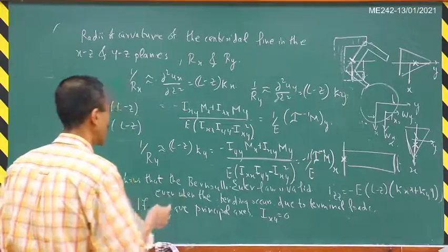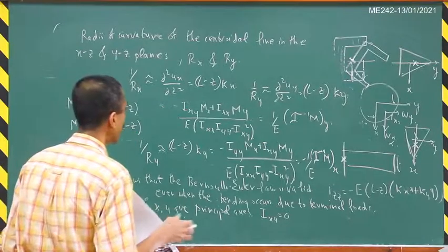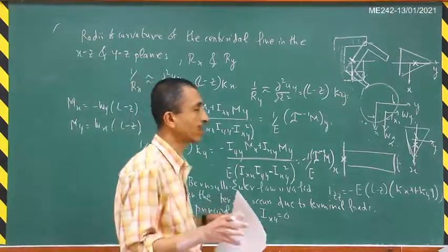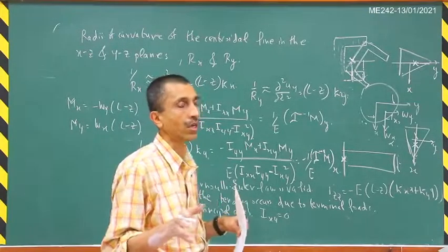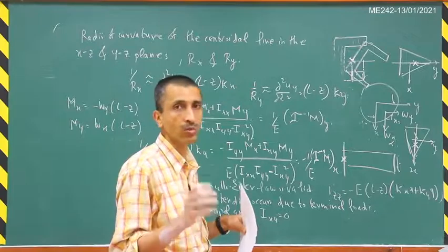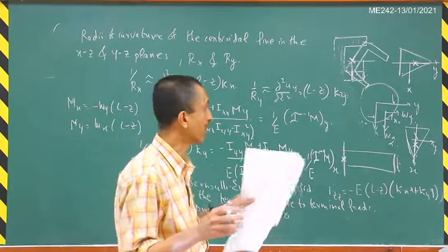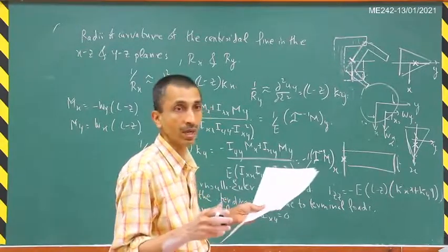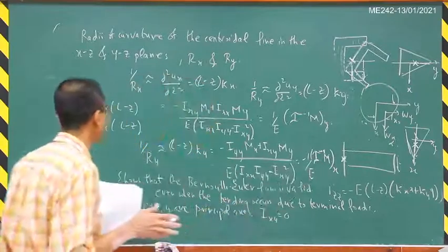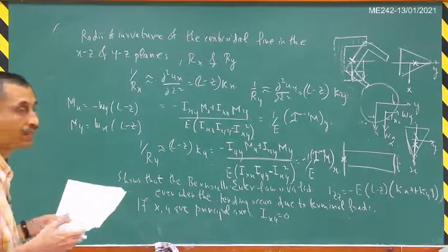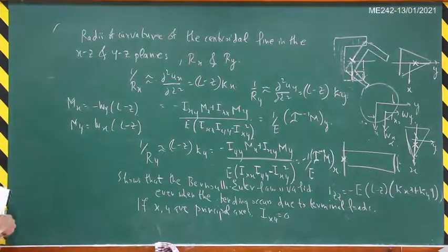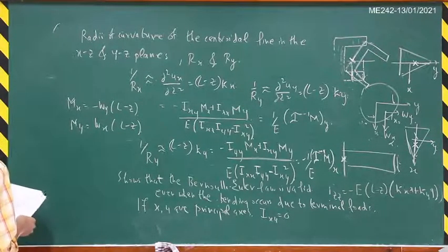So basically the same principle that guided us for pure bending can also be used in this particular case when there is bending by terminal loads, because even in this case you try to maximize the I, that is the moment of inertia, because the EI will still be the flexural rigidity.